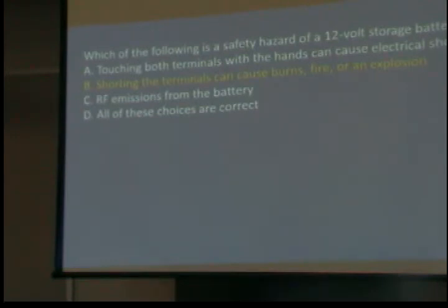You've just eliminated or reduced an explosion or fire hazard, okay? Anything that you put over those terminals to keep yourself from accidentally dropping a wrench on them, which can cause a problem, okay? I see people getting under the hood, laying wrenches on top of the battery, and I shudder, okay?